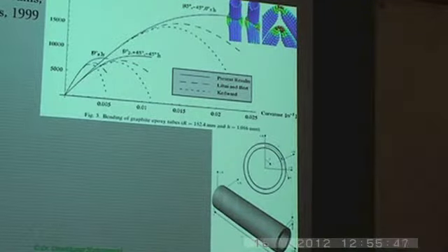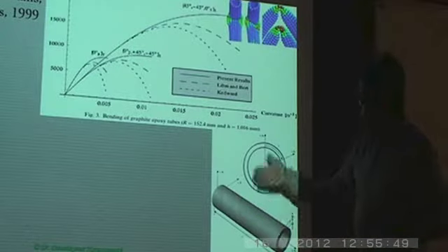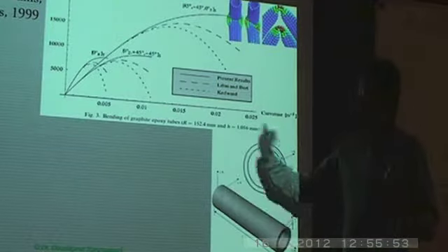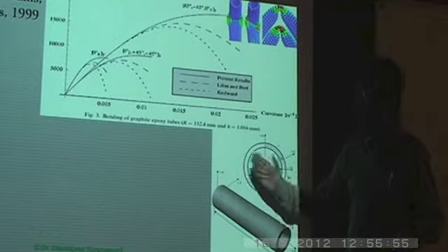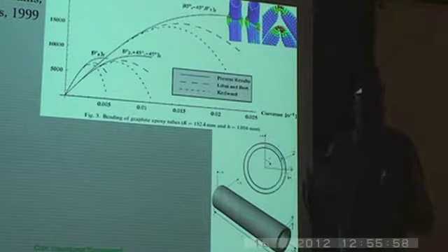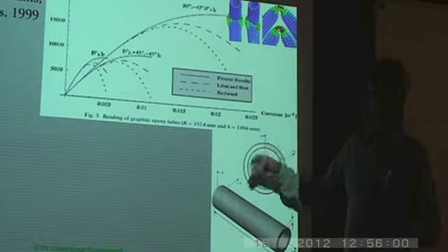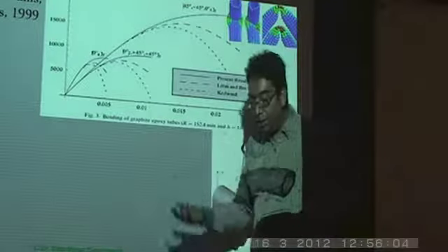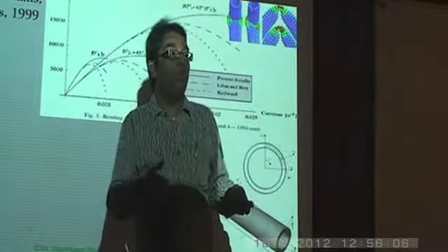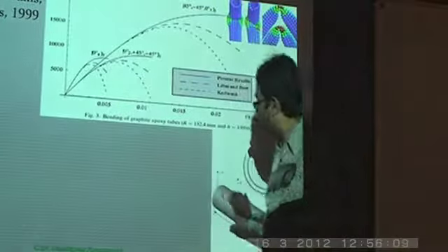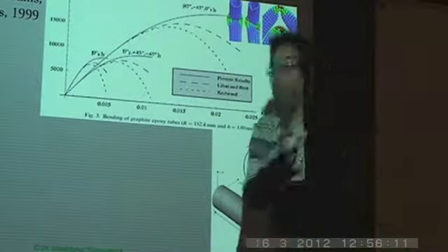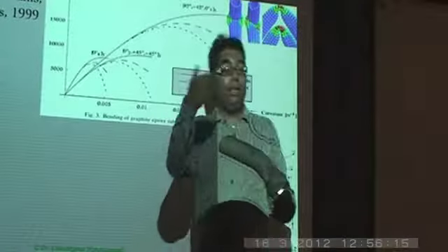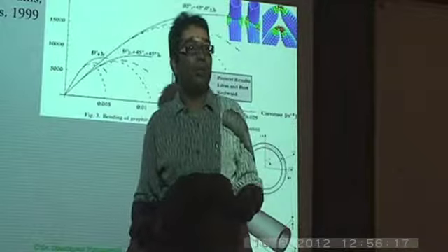So when you do that, first you introduce that, then you define the so-called 3D strains from the kinematics and bring the 1D kinematics into picture, the relationship between the 3D strains and the 1D strains. And then you substitute those 3D strains into the 3D constitutive law, which is basically the energy per unit volume of the structure, this particular structure. And then you integrate that over the entire volume and you minimize with respect to the warping measures. Then you get differential equations with respect to the warping.